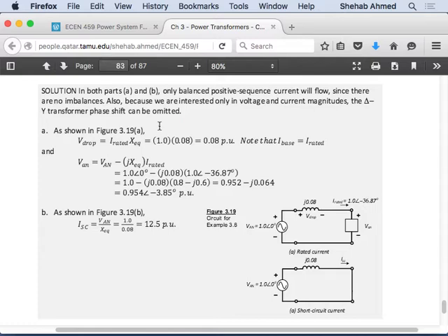And per unit, use the equivalent circuit as just a pure short circuit, basically. If I tell you to ignore transformer phase shift, there's no 1 to e to the j30 transformer anymore, right? You just put a short circuit, and if you're given the series impedance of the transformer, put the series impedance of the transformer. Okay? So here they said, okay, ignore it, but they said this in the solution. I will for sure tell you that in the problem statement.